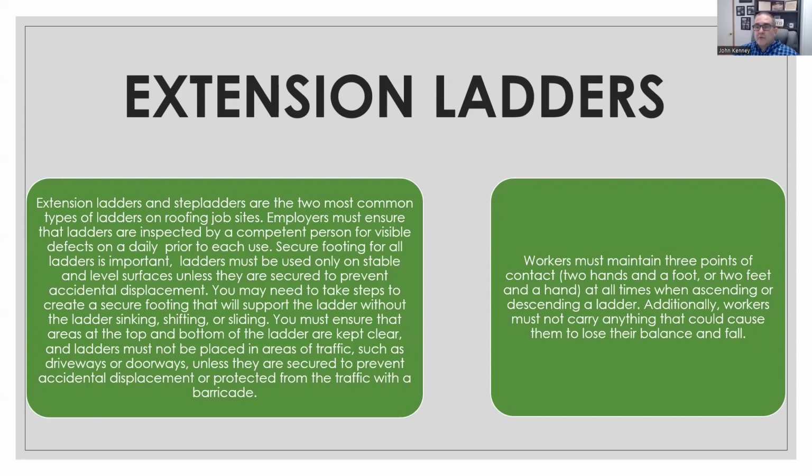Workers must maintain three points of contact, two hands and a foot, or two feet and a hand, at all times when ascending and descending a ladder. That is why you cannot carry stuff up a ladder and be in compliance. Additionally, workers must not carry anything that can cause them to lose their balance or fall.